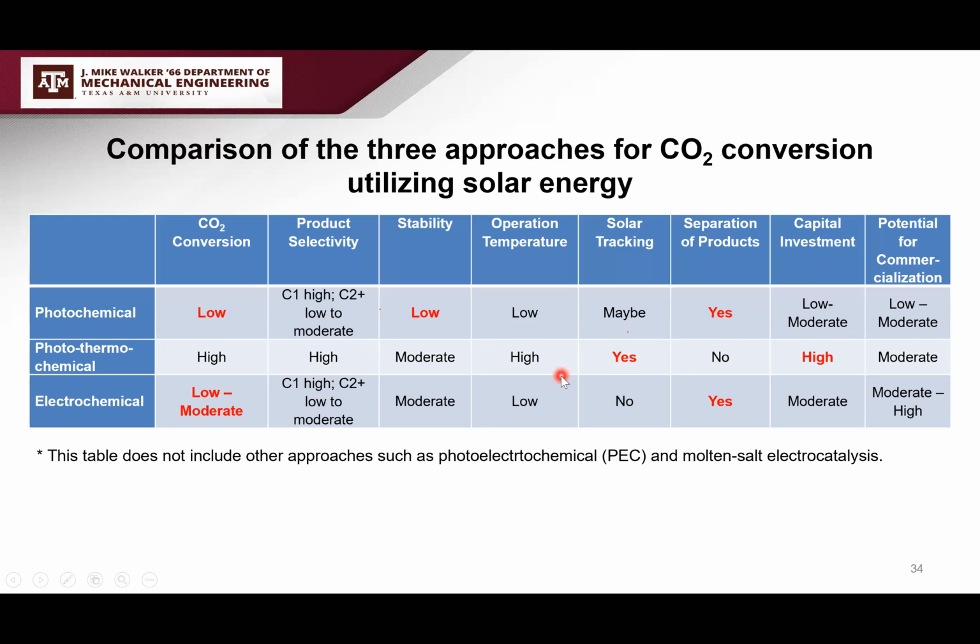But the downside is that the capital investment is high because it's concentrated solar. High temperature, some material cost, right? And also installing a concentrated solar reactor is high cost, and the solar tracking is an issue because for concentrating solar, you need high solar tracking. There's also a limitation.